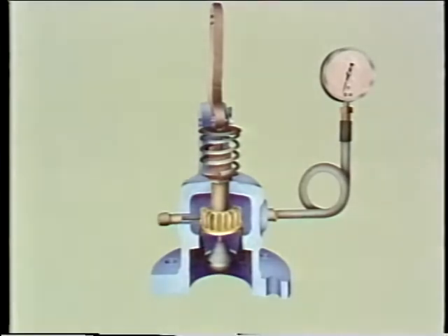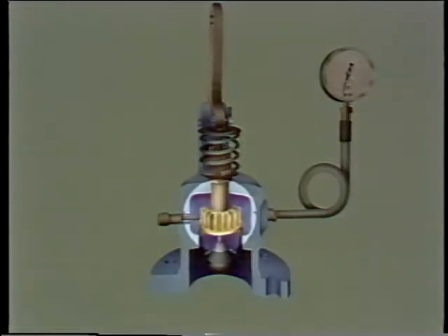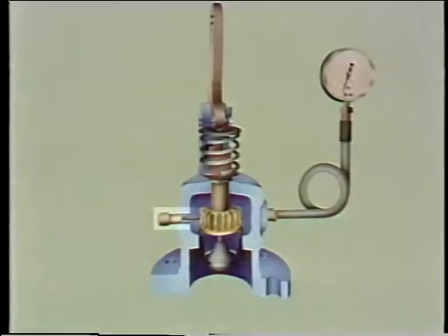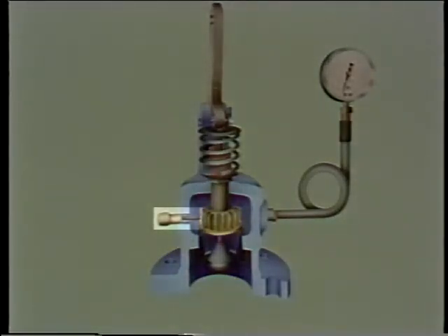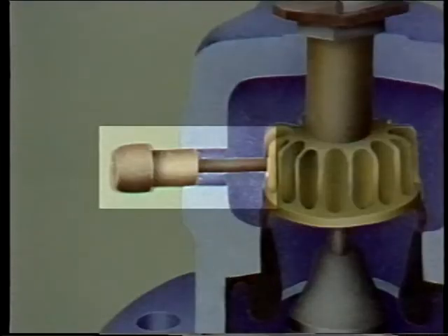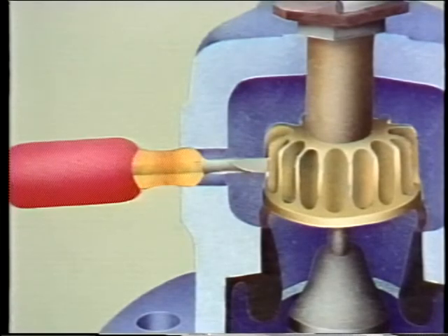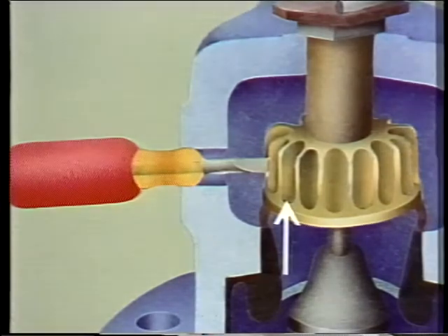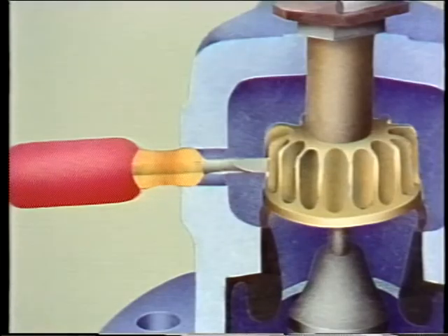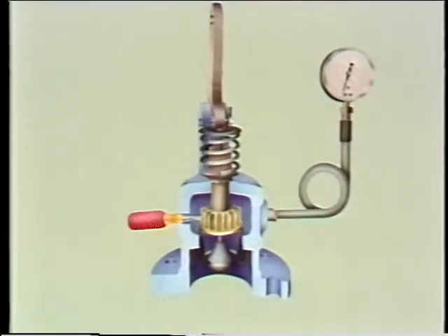One typical arrangement has a ring on the inside that adjusts the size of the opening in the valve. You can remove a plug in the body of the valve. This exposes the inside of the body, so the source of the blowing medium must be isolated and tagged before this step is done. The plug has a pin to lock the adjusting ring in place. Once it's removed, all you have to do is turn the ring with a screwdriver from the outside. Each notch equals a certain increase or decrease in pressure, depending on which way the ring is turned. The manufacturer's manual will tell you how this adjustment is made. When you replace the plug, the ring is locked at its setting with the pin.